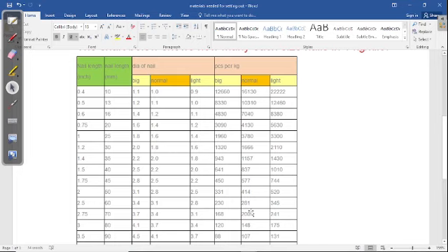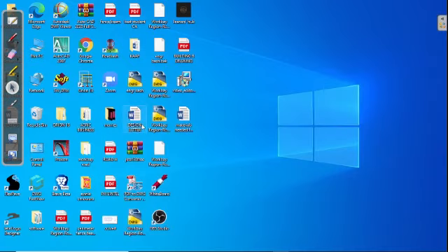So with this information, 1 kg will give us 200 pieces of 3 inch nail, ordinary, normal, meaning that 1 kg of 3 inches is sufficient for us to do this setting out, and half kg of 2 inches, which is around 207, is sufficient for us to finish our setting out for this drawing that we are estimating for the setting out material.